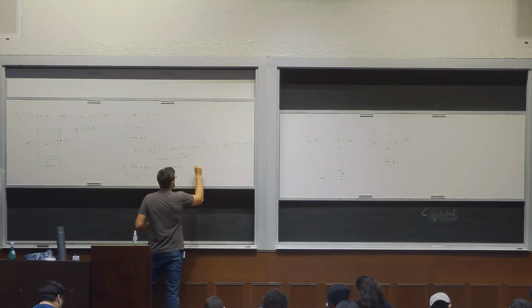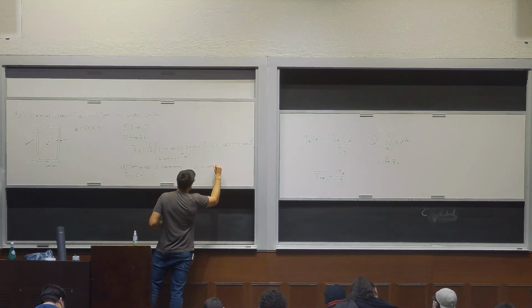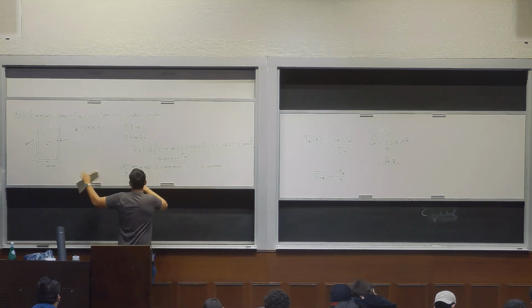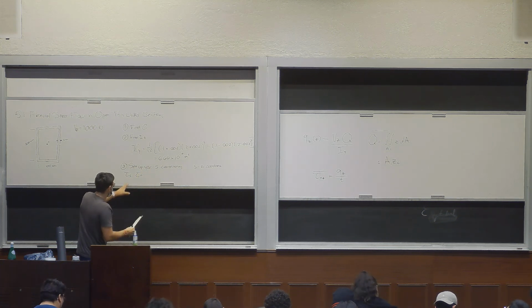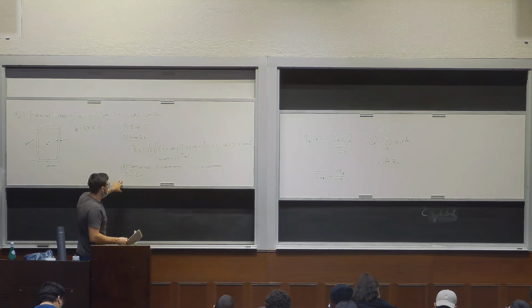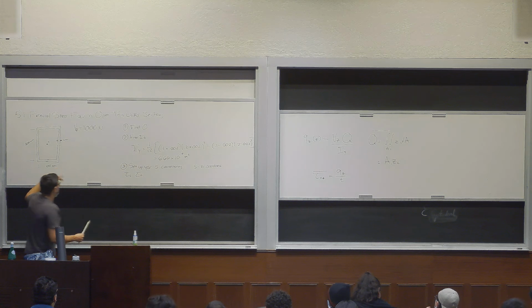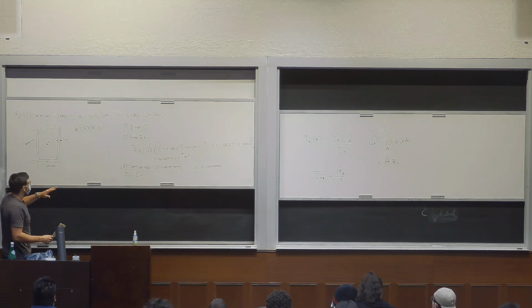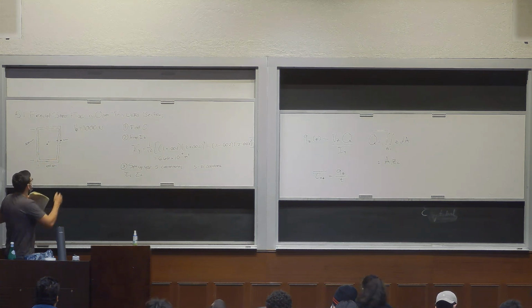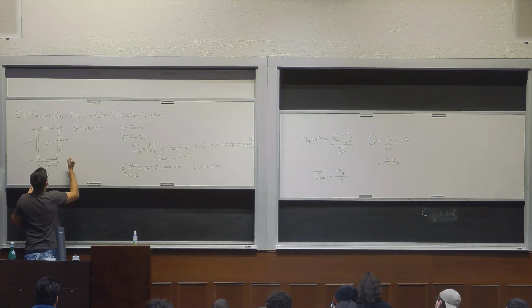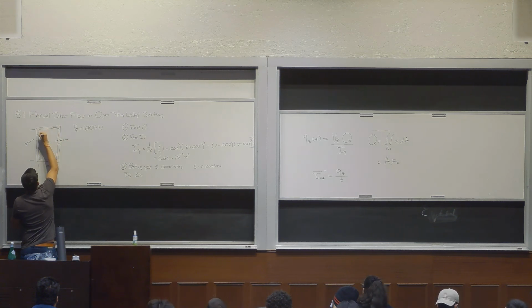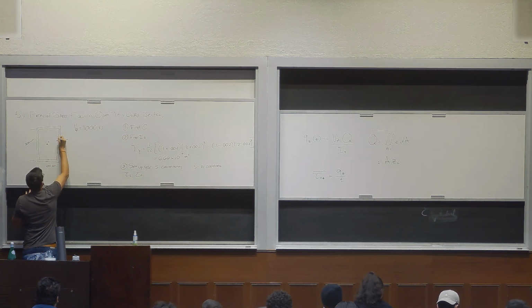We're using s n coordinates now, just for this. We're still going to use xy coordinates for all the other equations, but the taus that you get may not be tau xz or tau xy. The reason for this is that the s coordinate is the coordinate along the perimeter of whatever location you're looking at, right? So for example, S here points in this direction. S here points in this direction, and so on and so forth. And N points perpendicular to that. So here, it always points like this, right? So you guys got that, I hope.